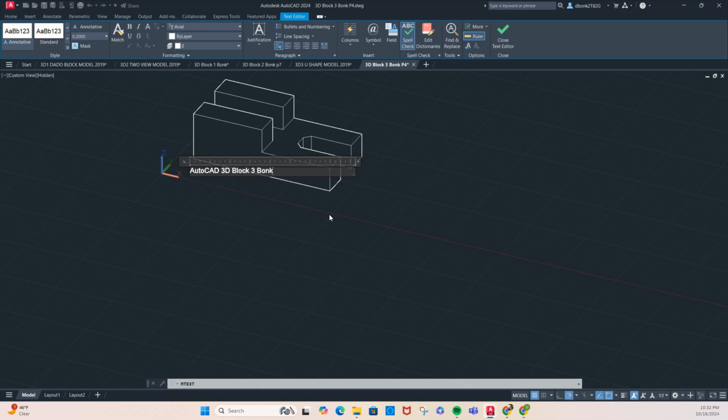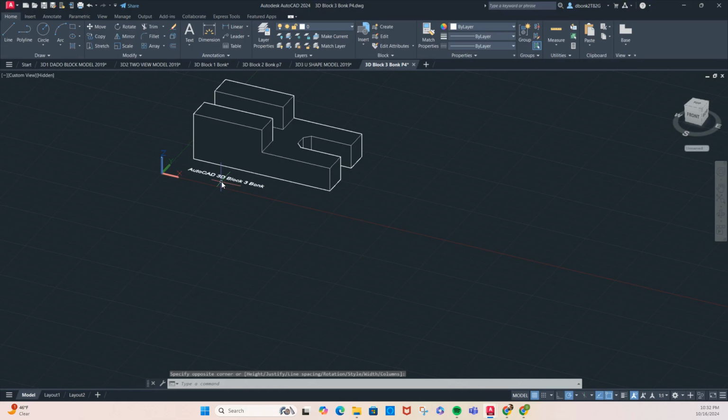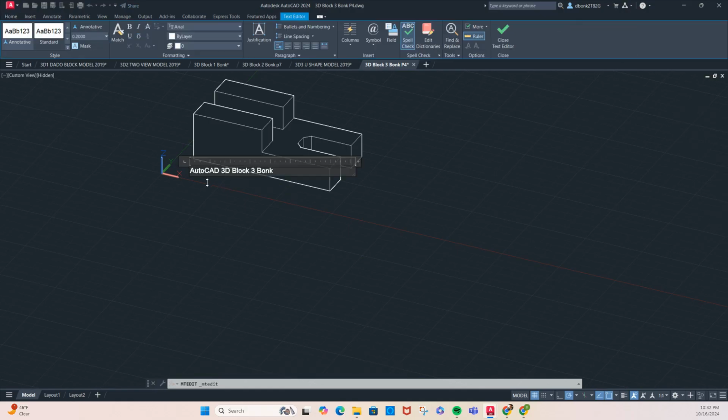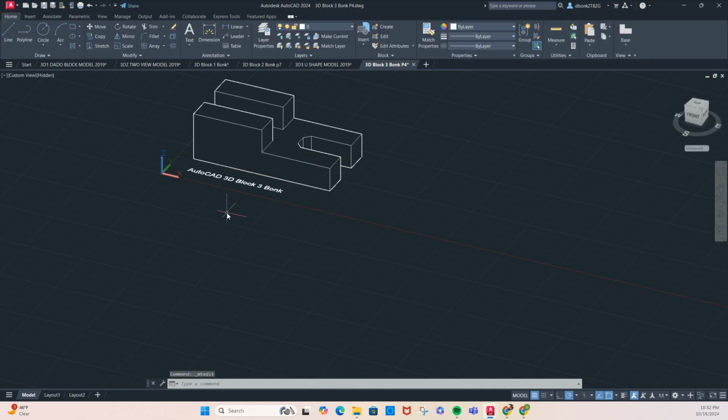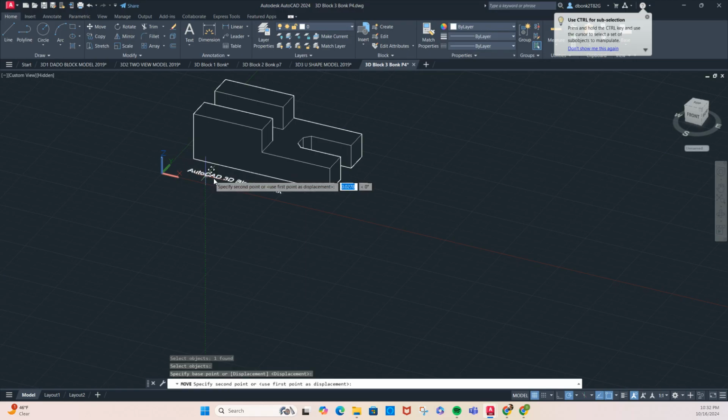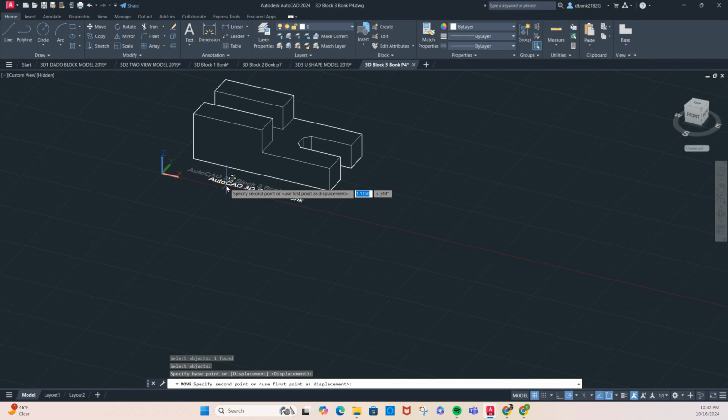and just use your naming convention. What I forgot to do was change this thing to the right size. Change it to 0.25 or 1/4 inch. And if you got to move it, click move, click the text, hit enter, click the text one more time, it'll grab it. You can center this thing up. If you'd like to change the font size, by all means, go for it.